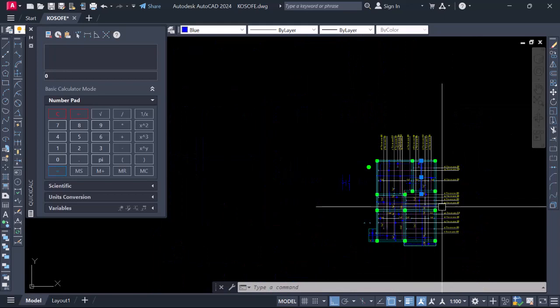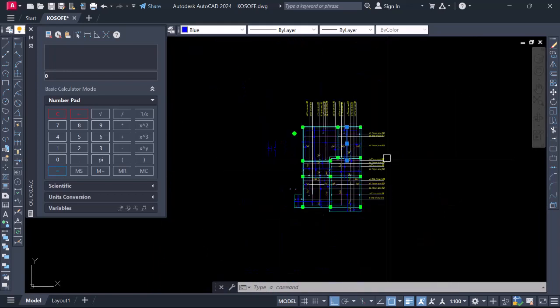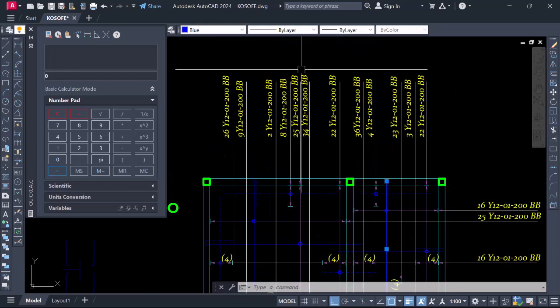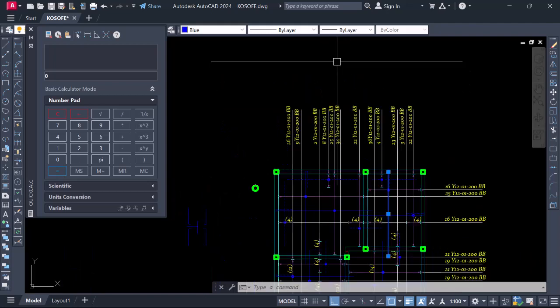Now coming to bar, like I explained in my staircase video, right? Denoting your bar number, there are certain things you're supposed to understand when you're doing a bar number. These are 3 factors. Number 1 should be the size. Number 2 should be the length. And number 3 should be the shape. All right. Number is another thing that you should consider, but it shouldn't be much considered,